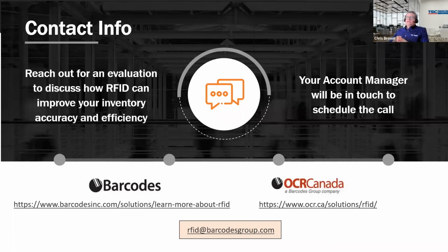Yeah, there's sort of 3 temperature ranges. This gets complicated. There are 3 different temperature ranges you need to consider. One is in which temperature range will you actually be reading the tags. Temperature range 2 is which temperature range does the RFID portion of the tag need to survive. And temperature range 3 is which temperature range do the physical tags themselves need to survive.